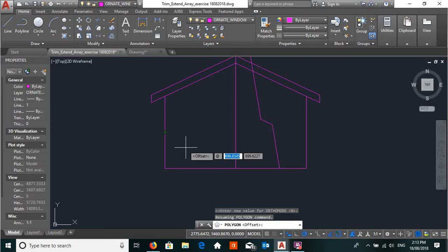There it is in gray, and the blue section is prompting us for our X distance, which is moving to the right side of the base point. So that is a positive 1050. We type in our comma, which locks that in and shifts to the Y value, and we type in 1650 and press enter.